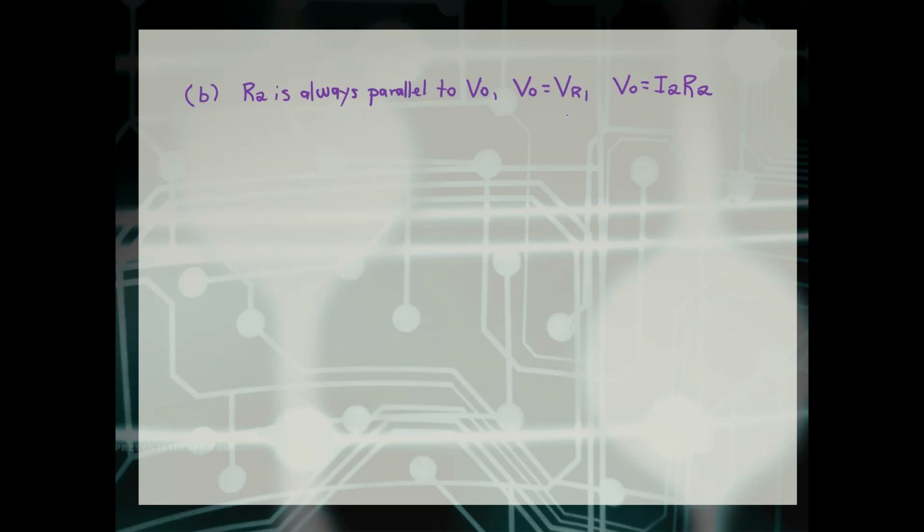If you manipulate that equation for I2, you'd have I2 equals V naught over R2. Now, the thing about this current value is that the current through that right branch is always going to be constant. The reason it's constant is that the battery voltage is a constant.